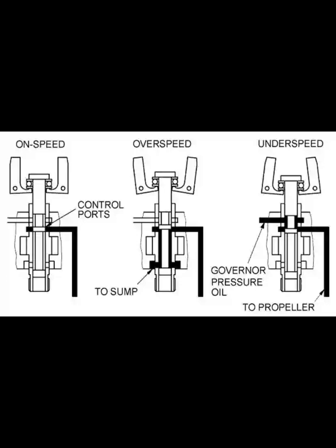What is blade tracking? Determining the position of the tips of the blades relative to each other. Do the counterweights on a constant speed propeller increase or decrease the blade angle? They increase the pitch of the blades.